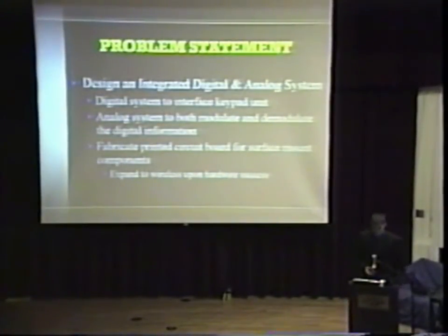In general, this project can be described as a design of an integrated digital and analog system. The digital system needs to interface a keypad unit. From that, the analog system is required to modulate and demodulate the digital information and incorporate any filtering that it'll need. It'll also have to be placed on a printed circuit board, which must be fabricated for all the surface mount components. And upon success, it will be expanded into a wireless system.